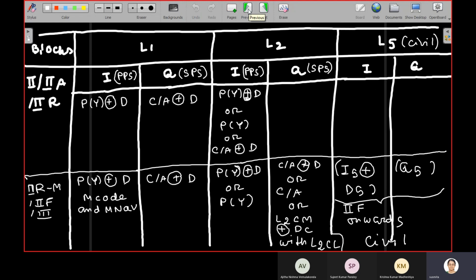With the modern design, now you may ask why we require such a complicated design. All the new signals do not have BPSK modulation. BPSK is the simplest modulation, where we just multiply plus or minus 1 with the carrier. They have a more complex modulation scheme. Now you can ask why we are varying the chipping rate and code period.